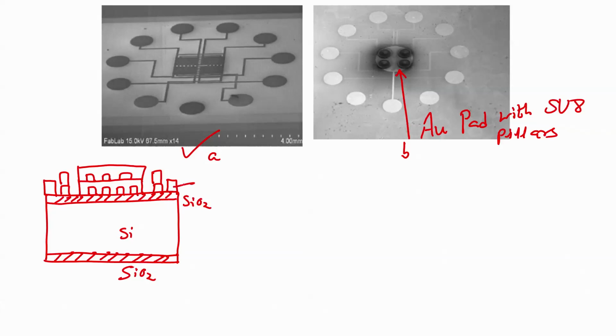Then what is this one? This is again SiO2, right, insulator. Then what is this one? This is our micro heater. Then what is this one? This is your interdigitated electrodes. What is this one? This is your piezoresistive material, correct. This is your A, and next is we have to deposit gold, but like I said, we cannot deposit metal on piezoresistor. So, what is the next step?